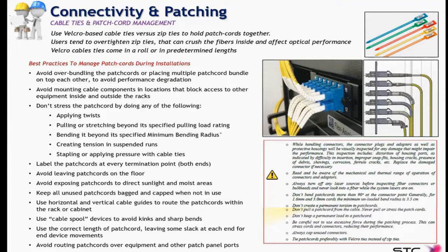Avoid leaving patch cords on the floor. Avoid as well any patch cord exposure to direct sunlight and moist areas. Keep patch cords in their bags and capped. Do not remove the dust caps from any connectors unless you are using them. Use the horizontal and vertical cable guides of the equipment as well as the cable spools to avoid kinking and sharp bends. Always use the correct length of patch cords according to the manufacturer instructions.